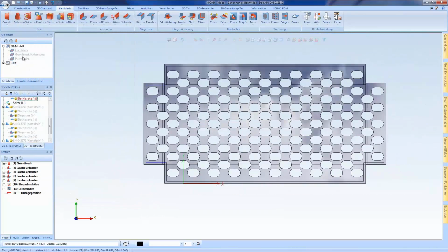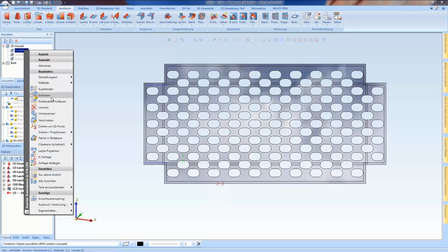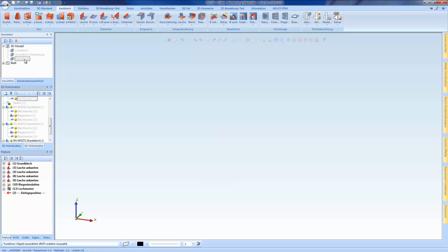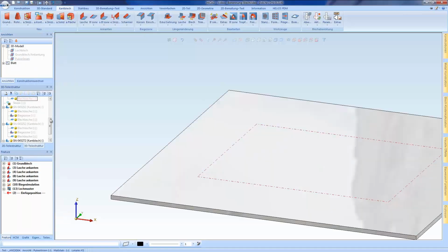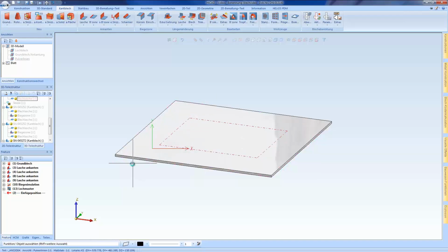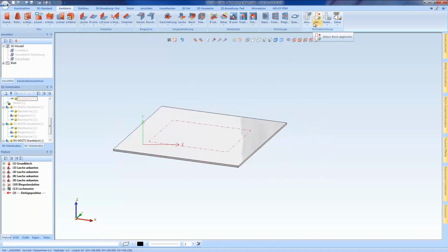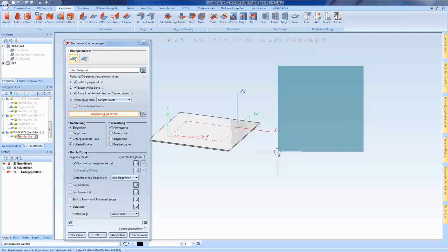We will now have a look at the new enhancement in the area of the powder marking lines. For this, I will show another sheet on which I have already set a powder marking line. When creating a powder marking line, I can of course define the line and color type. However, I cannot define the coating on which the powder marking line is on. The reason for this is that the coating is defined by the sheet flange. This means that if the sheet flange is, for example, 10, the powder marking line will also be at 10.